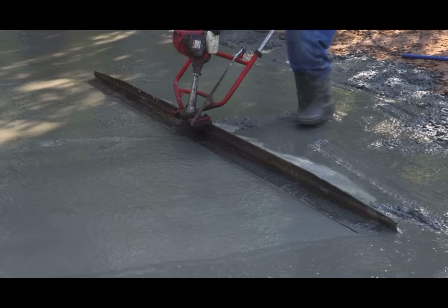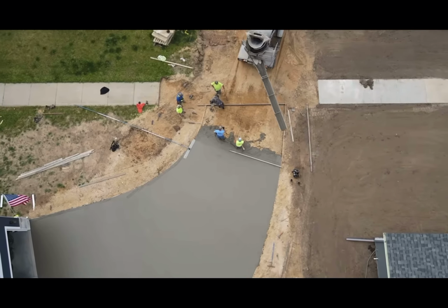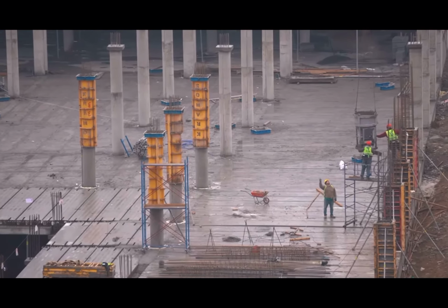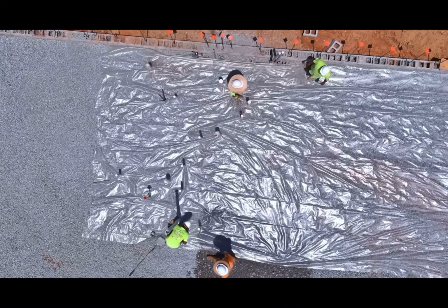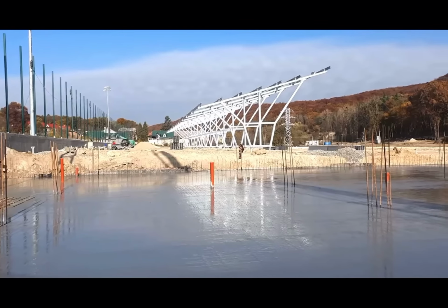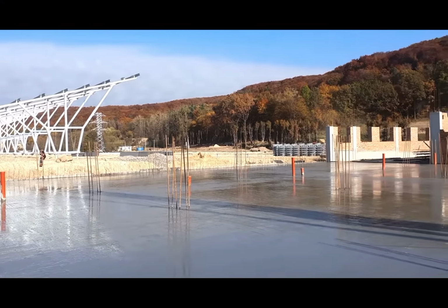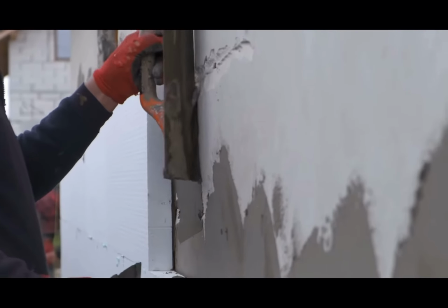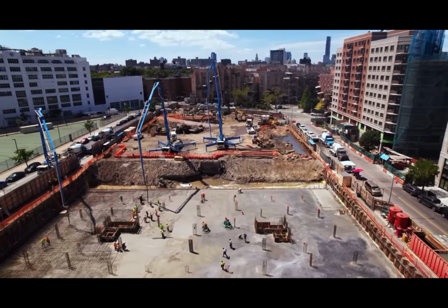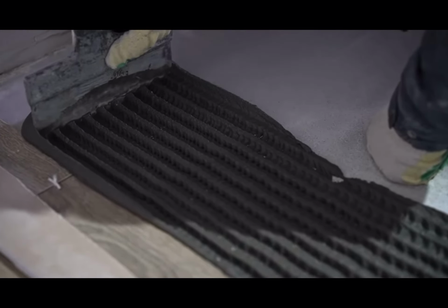Once the concrete is placed and compacted, it needs to be cured. Curing is the process of maintaining adequate moisture and temperature conditions to allow the cement to hydrate and gain strength gradually. This typically involves keeping the concrete damp or covering it with curing membranes, blankets, or plastic sheets. Curing can last for several days or weeks, depending on the type of concrete and the desired strength. After the concrete has cured sufficiently, various finishing techniques can be applied to achieve the desired surface texture and appearance. This can include techniques such as smoothing, leveling, troweling, or applying decorative finishes.